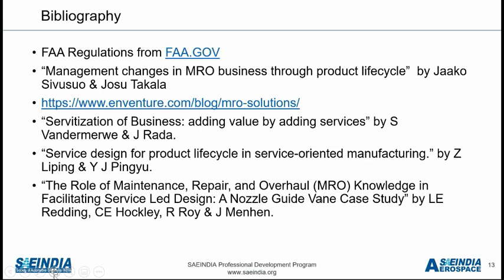A check is a minor check, where they will simply see the things, see the parts and all. B check is wherein they will do more detailed maintenance or more detailed inspection. The C check is typically a 2 years check. So either 2 years or 5,000 or 6,000 flight hours. If an aircraft has run for 5,000 or 6,000 hours or 2 years, whichever comes first, they will do the C check.